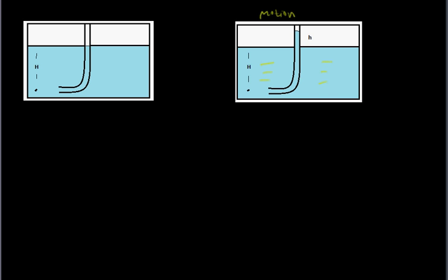That way we can determine the velocity given the height of the fluid, or given some pressure measured with a pressure transducer, which is probably the more realistic way. You would measure the pressure difference with a pressure transducer, and then use that information to calculate the velocity.